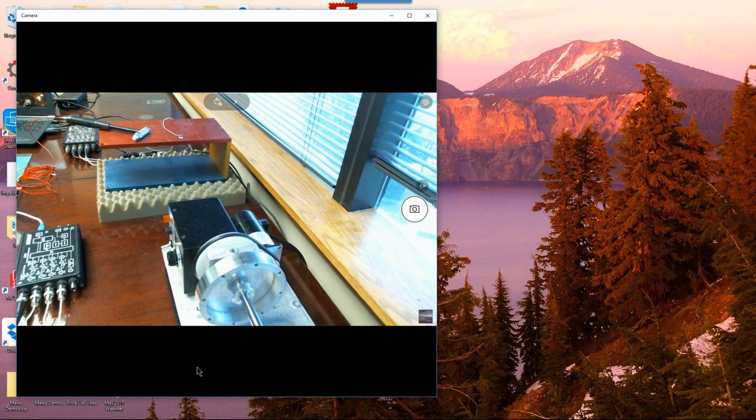And so the title of our talk is Repeatability. This is something a little bit new that most people don't think about or even be concerned about when they're taking data on a structure with an impact hammer. So the question is, am I impacting at the same point all the time as I rove the accelerometer around and take data on the machine or the structure?